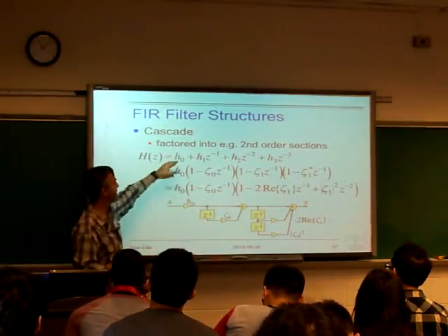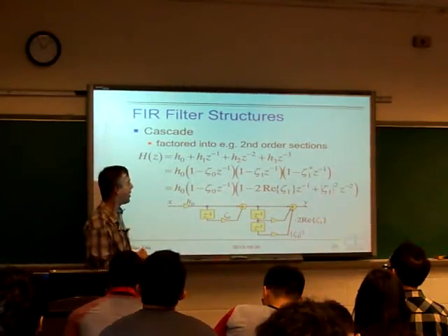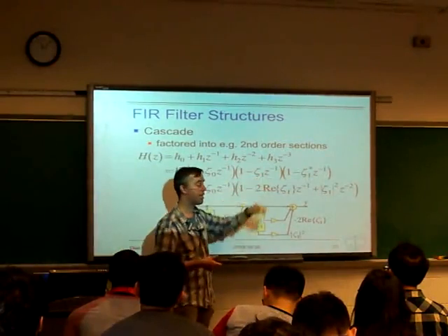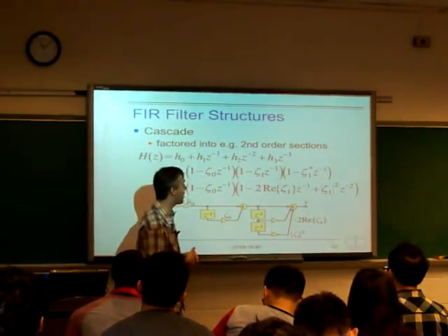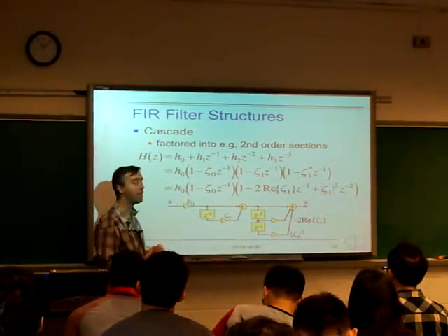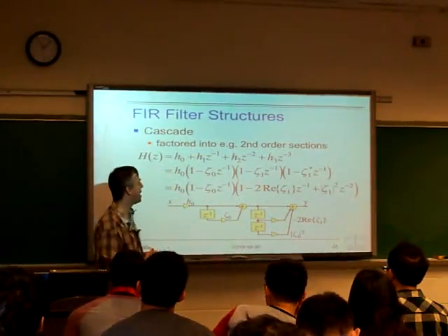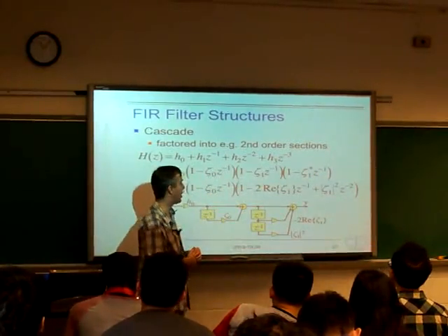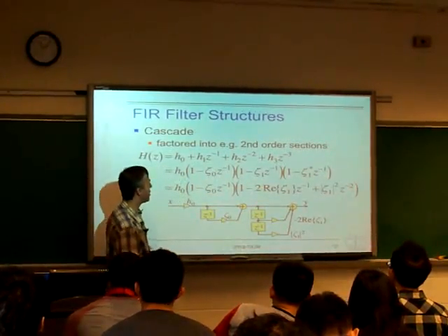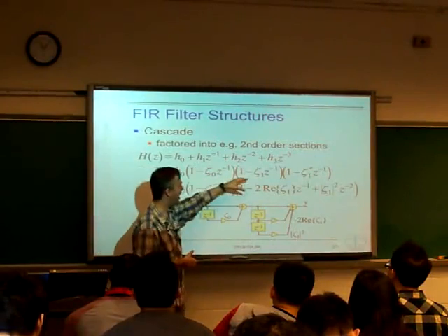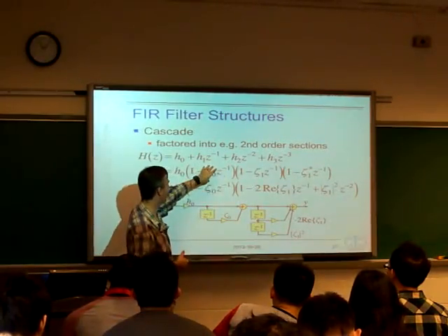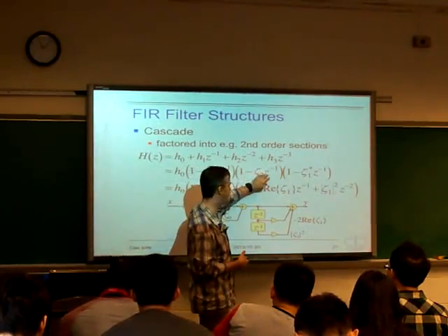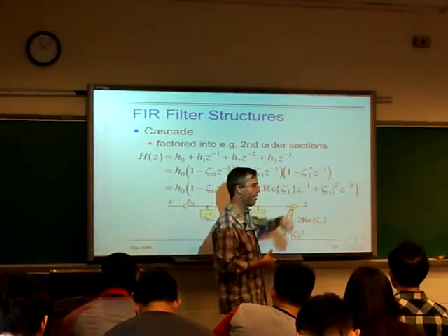If the impulse response is real, then we know that if the zeros are complex, they're going to have to occur in complex conjugate pairs. Although if they're real, they can occur individually. So, for instance, let's assume we have a single real root and a pair of complex conjugate zeros. Then we could express it like this, which would be like first filtering with a single zero here, then filtering with another zero, in this case complex, and then with another zero, which is the conjugate of that.